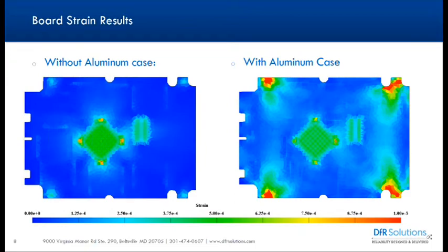If your environment is, think of a data center or some kind of big server farm, then you don't necessarily get up to the temperatures that you see in the test. So the early failures that you see in the test might not actually be correlated to what you see in the field, because in the field you'll only go up to, let's say, 60 degrees. And that delta T might not cause enough problems for you.